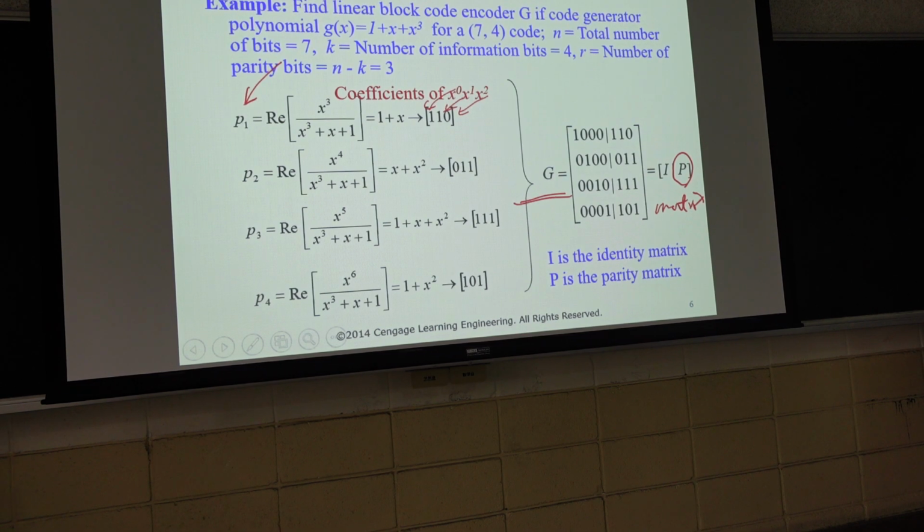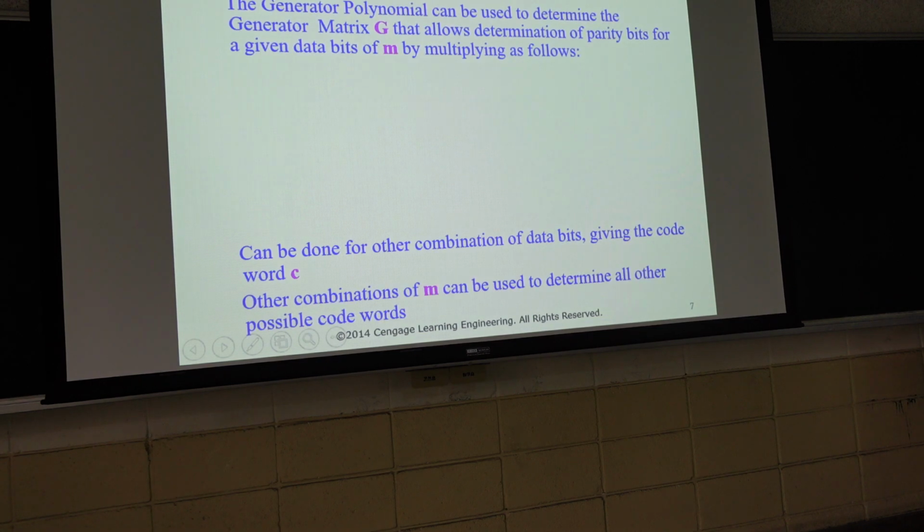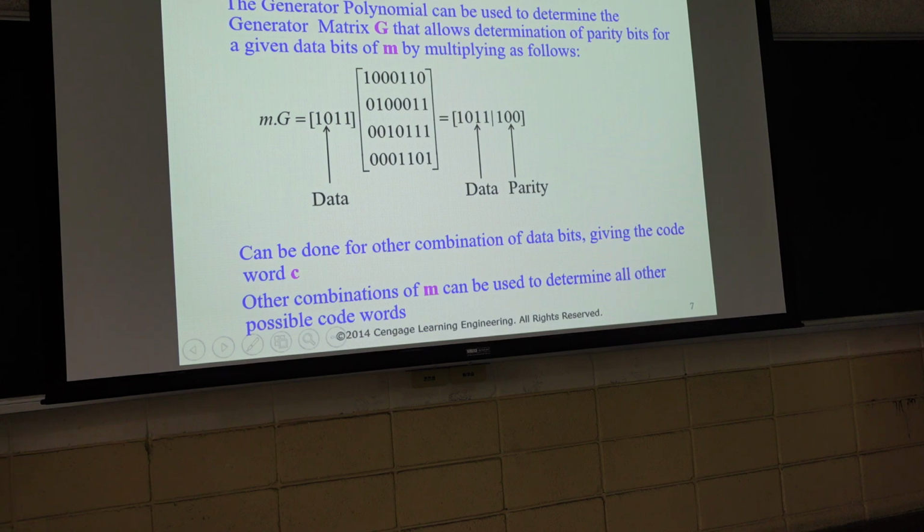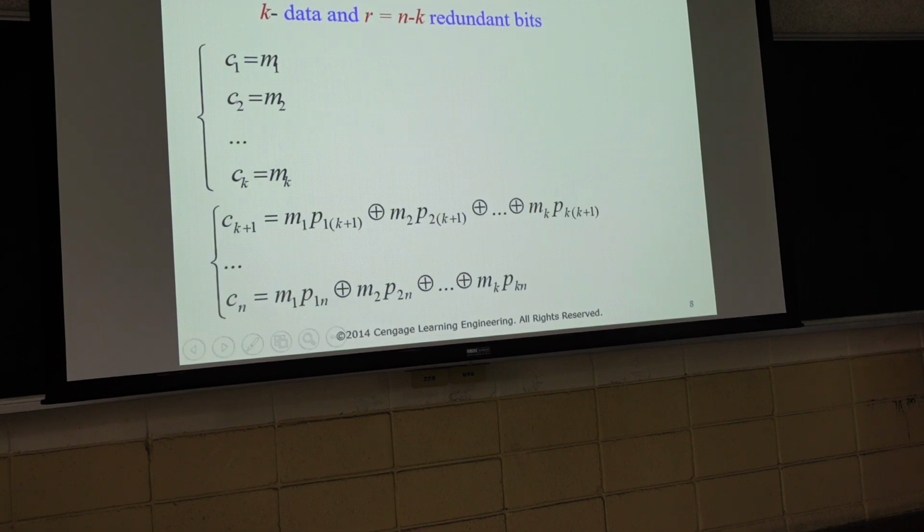About the information, we directly have the generator polynomial G(x). You also need to notice the value of k and the value of r. All the information here allows you to do the calculation. Once we have G, we can generate the codeword by multiplying the message by G, and then you have the code vector. I think you can see the relationship as well.